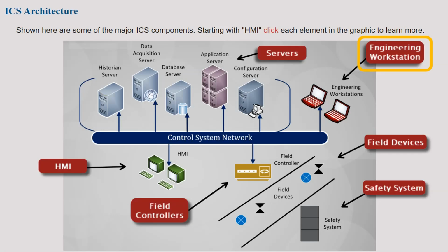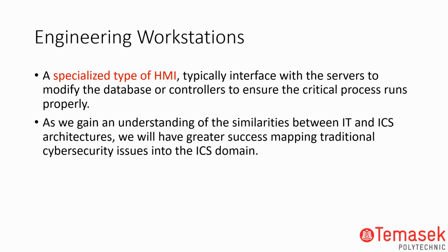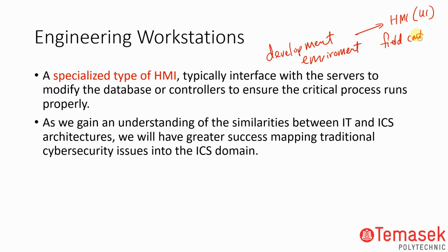Next, the engineering workstation. So what's an engineering workstation? To put it bluntly, it is a development environment for the HMI, which is the UI portion, and the field controller, which is the logic portion.